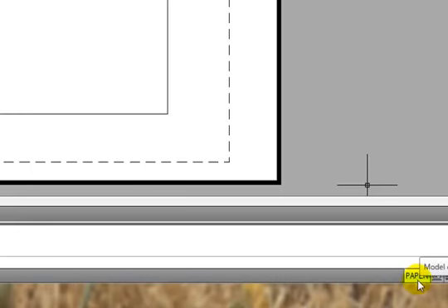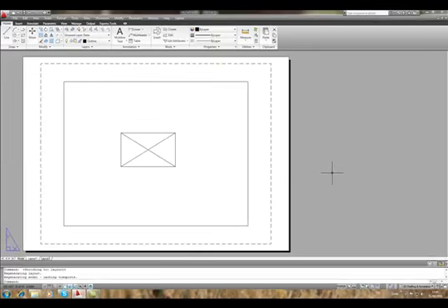We are in paper space in layout mode, as indicated by the button on the right hand side of the taskbar here, and we can also tell we're in paper space from the appearance of the UCS icon, which is no longer shown as single lines but rather as a triangle, with the X and Y coordinates shown on the horizontal and vertical sides of the triangle.